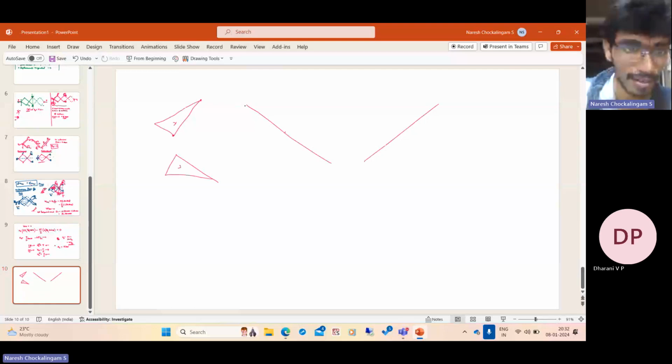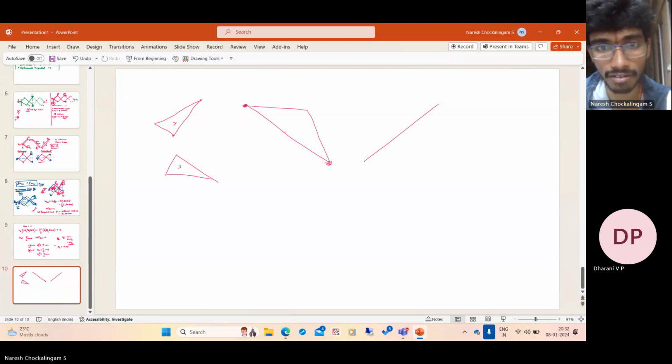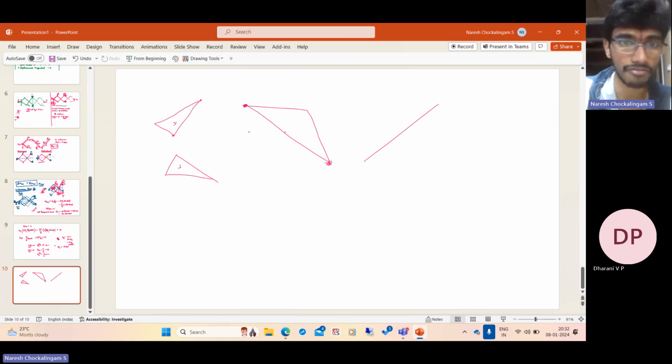And this is pin connected. So here you should have 0 bending moment. Here you should have 0 bending moment. And in the middle you have some maximum bending moment. It is plus or minus, we don't know. But let us just take this, and there are no forces in between. So the bending moment diagram of the redundant structure is like this.